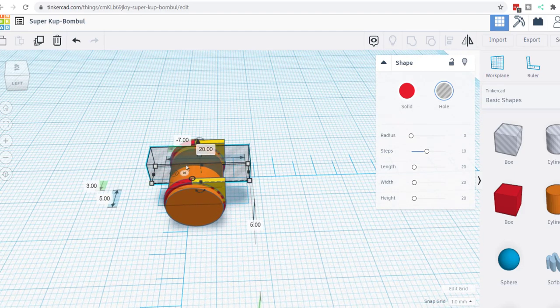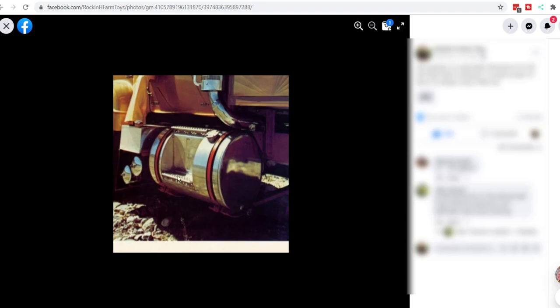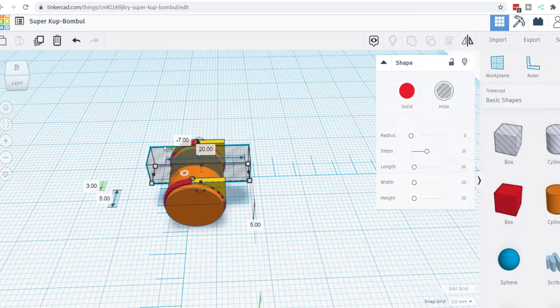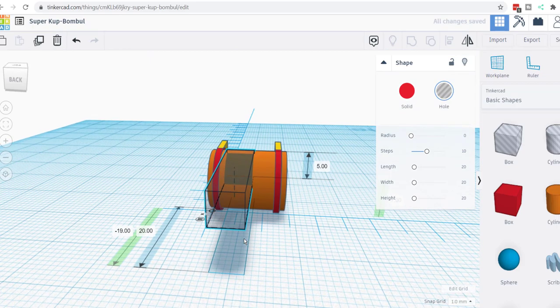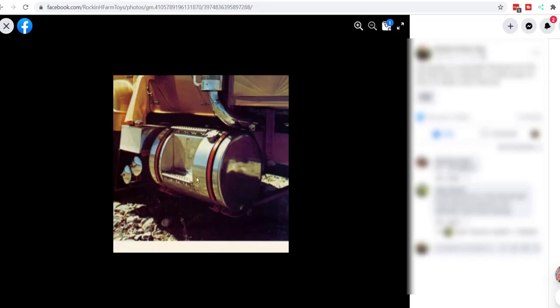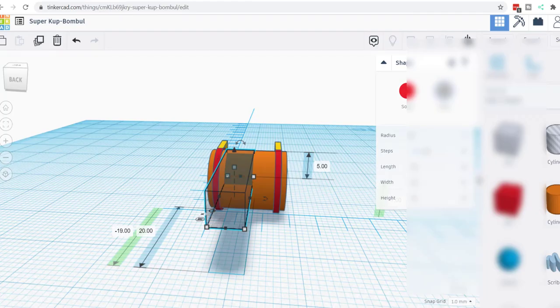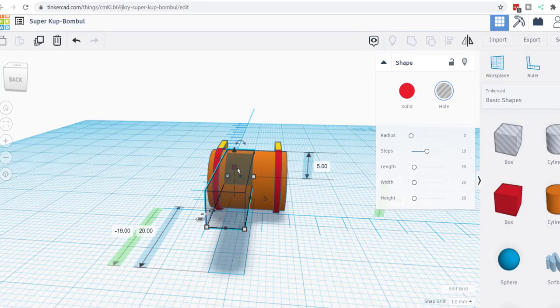Now you see this shaded part here? We're only going to make this much of our 3D tank shaded. So I'm going to click on that, use my arrow key to move that out. And now we're going to make our step. So to make a cutout, like you see here, this is what's called a hole. And in Tinkercad, this is how you make the cutout. This thing called the hole here, this clear area, is how we accomplish that.